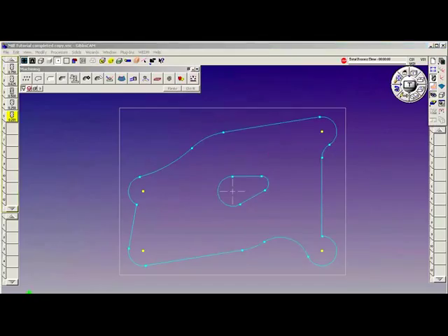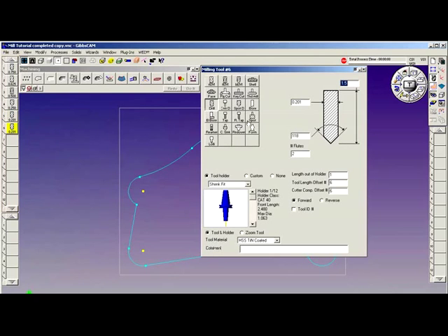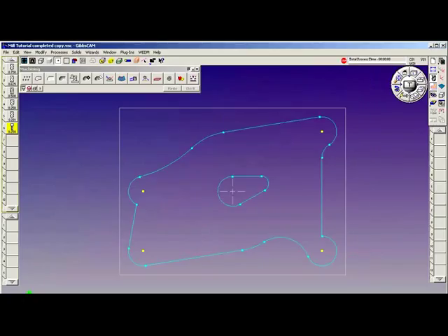Now, tool number 6 is going to be our tap. This tap is going to be a rigid tap, 1.5 inches long, 0.25 diameter, and the threads per inch, as I mentioned, will be 20. I'm going to give myself a 40 thousandths lead, and again, using high-speed steel, tin-coated. All right, 6 tools.